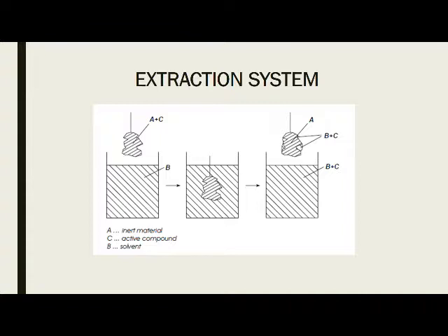So the extraction material is not a homogeneous substance but consists of a lot of capillaries. At the beginning, the solvent enters the capillaries and dissolves the extract. A solution with high concentration is produced here. Because of diffusion, a concentration change between the solution in the extraction material and the solution surrounding the solid particles takes place. So at the end of the process, still a certain amount of solution consisting of solvent and extraction substance is retained in the solid particles because of adhesive forces, also known as underflow. This is the reason why practically no complete extraction is possible.